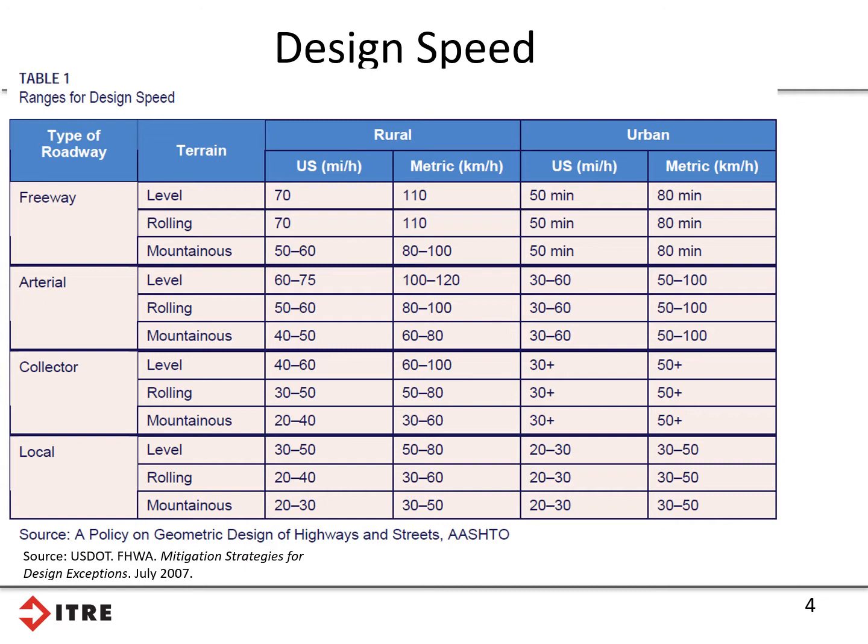And generally drivers will know the design speed. They may not think of it as the design speed, but they will experience what that maximum speed is, particularly through horizontal curves, as they push that boundary of feeling the acceleration and gravitational forces in the vehicle, and have some sense for what the design speed is for a given roadway. Curves are the primary way that drivers will experience the design speed.